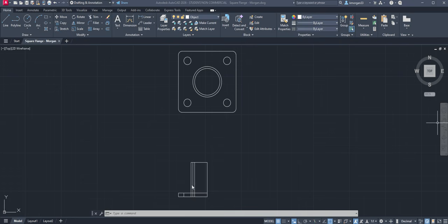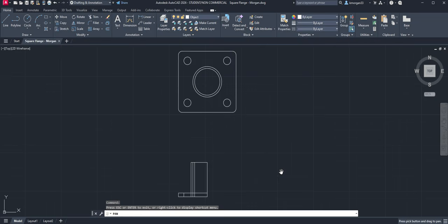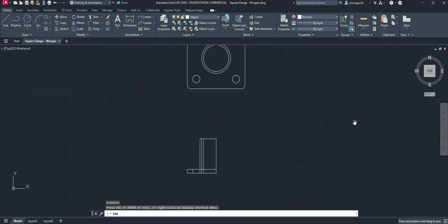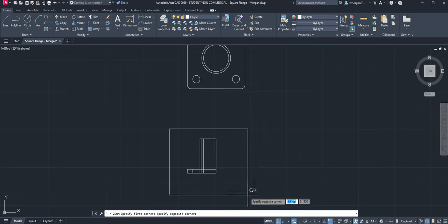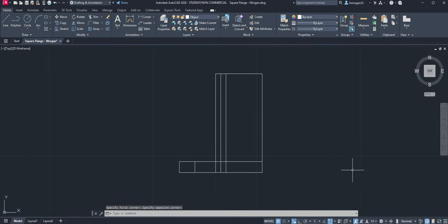Now we are going to navigate to this little thing. So I'm just going to go ahead and get my hand and then pull it up a little bit, escape out of the hand. And of course I'll go to our little window so that we can see this. Alright, zoom in and go ahead and save that. Alright, the next thing is to trim off. So we go back to our home, modify, your trim is here. I'm showing you step by step where the trim is, and try to remember, okay? So you know where they are.